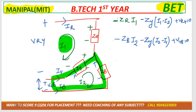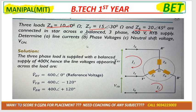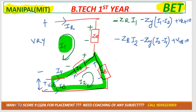After this, as you can see in the question, voltage is given, that is 400 volt. This is the line voltage. So we take VRY as 400 angle 0. Second, I told you that is minus 120. Third one, you can take it 400 angle minus 240 or plus 120. That's one and the same thing, right? After this, we can substitute the value of VRY and VYB, ZR and ZY. Yes, can we convert it into matrix form?